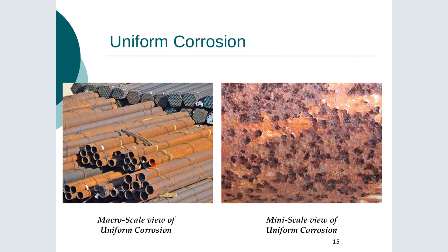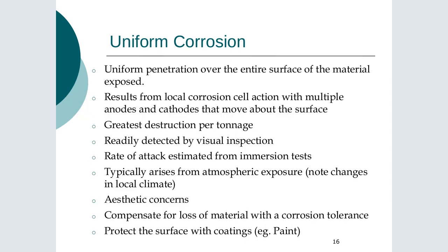We'll figure out the pipe thickness. We'll design that to a known standard, whether it's ANSI or a European standard. And we factor in then a corrosion tolerance. So you put in material that gets essentially eaten away. When you look at it close, you can see that mottled surface. That is the material as it flakes off, and there's deposits on it, etc. So that's not really a concern.